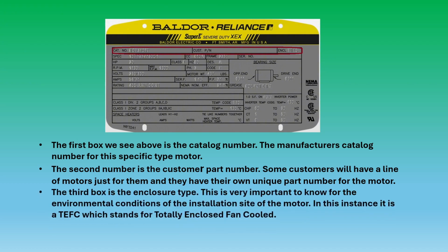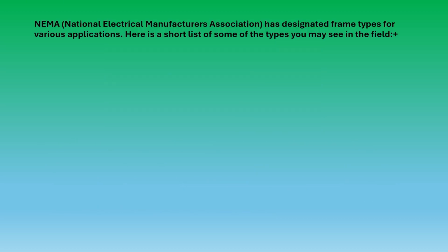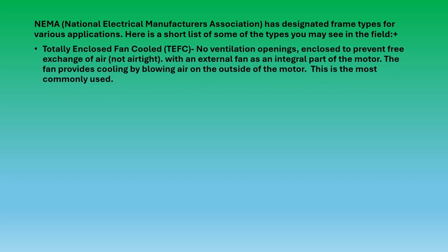This is very important to know for the environmental conditions of the installation side of the motor. In this instance, it is a TEFC, which stands for Totally Enclosed Fan Cooled. NEMA, the National Electrical Manufacturers Association, has designated frame types for various applications. Here's a short list of some of the types you may see in the field.